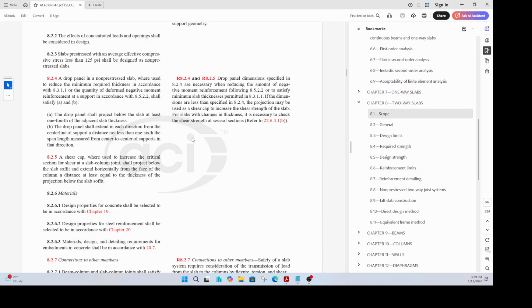That's a slightly deeper topic, but the idea is if you have a slab like that with your column like this, right? And there is load on the top, so the load is trying to push the slab down through the column, right? And what happens is the slab will start to crack in that direction at an angle of 45 degrees, meaning there's something called a critical plane, which is at d by 2 from the face. Let's say this is d, then d by 2 from the face of the column. You have your critical section 1-1, critical section 1-1.